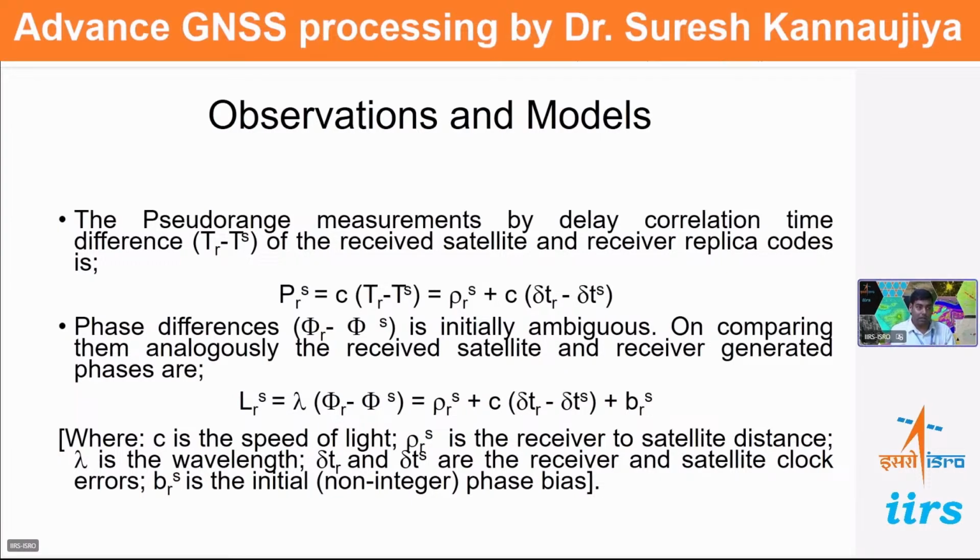When I say latitude, longitude, and height, it is with respect to the prime meridian, the equator, and the ellipsoidal height of the Earth. But in our case in geodynamics, we also use geocentric coordinates, where the data is referenced from the center of the Earth. That's why it is called geocentric.